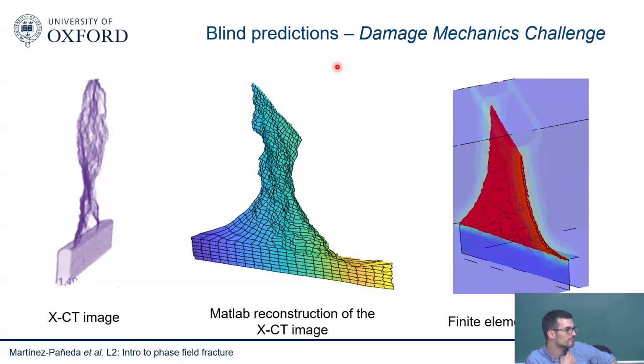This length scale parameter, the material property, if we calculate it from the formula that you have shown, the value generally comes very high. It depends on your material. It could come high, depending on the fracture properties. So first we have to decide mesh size or length scale parameter, which one should we choose first? No, the length scale is a material property, so you don't have the freedom to pick that one. If you have a given material and you're going to be predictive, you need to take the value that comes out of the equation. And then what you pick is your h.